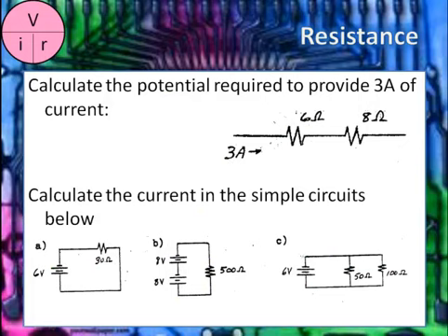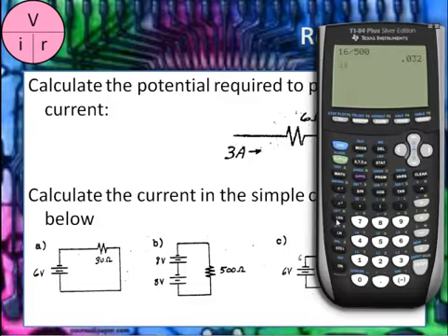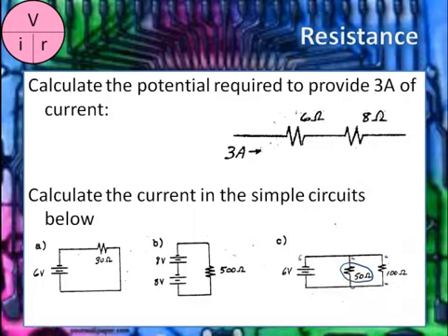Let me clean this up a little bit. We've got 6 volts, 6 volts, 6 volts, 0, 0. So through this first resistor, I've got 6 volts over 50 ohms, and so that works out to 6 over 50, 0.12. So I'm going to say 120 milliamps runs through here.